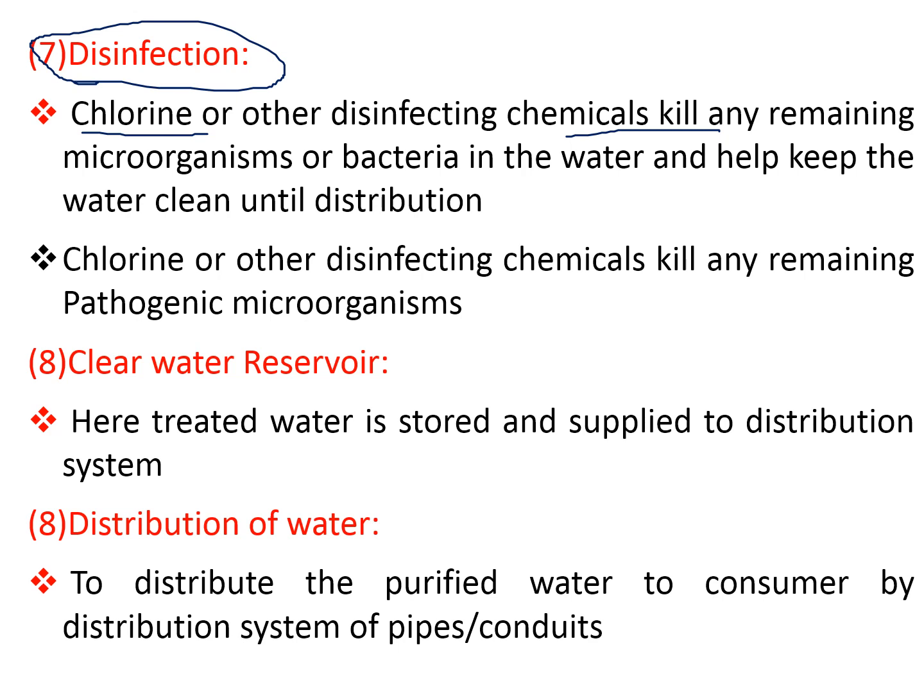In the distribution system, if further recontamination takes place, the residual chlorine keeps it safe against further contamination. It is also cheaply available, has good disinfecting power, and has residual power. Due to that, in India chlorine is the widely used disinfectant.